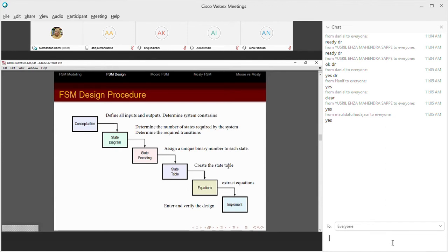So if you combine present state and inputs, say it is 4, altogether 4 variables. For example, you have two inputs D, N, and then you have states S0, S1, S2, S3 that require 2 flip-flops or 2 variables. Still you manage to come up with the state table, but if it's more than 4 variables, then skip the binary encoding or the gray encoding, just go to the one hot method.